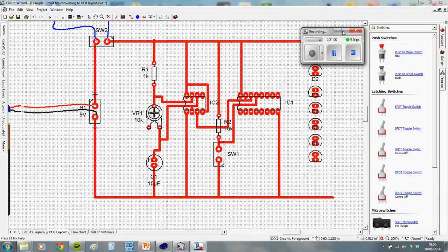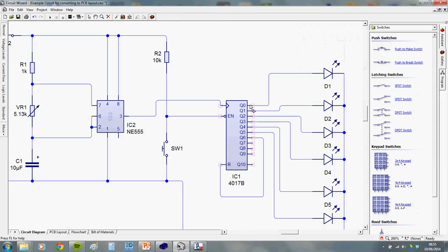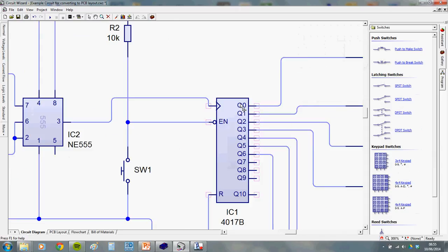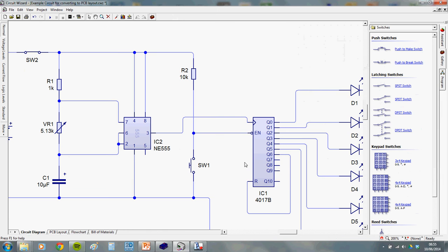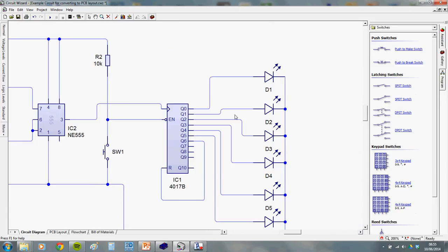Right, actually I came back a little bit early. I realised it was important to tell you that again, because these chips are laid out in a nice logical order, look, output 0, 1, 2, 3, 4, they're all in a nice order on here. Annoyingly they're not in that order in real life. So for instance, if we hover over output 0, in real life it's actually on pin 3, as it says there in that label.